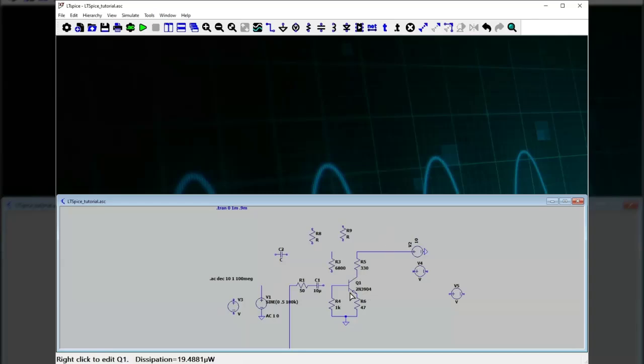And the thing that some people might have issue with maybe is the BJT. So where do you get that? So under Edit Components, if I edit, and that pop-up that you can't see, and you come down and select Component, and then you get another pop-up you can't see, and then go to NPN, in one of the third or fourth column, NPN, you click that, and then Place, and you will see an NPN transistor.